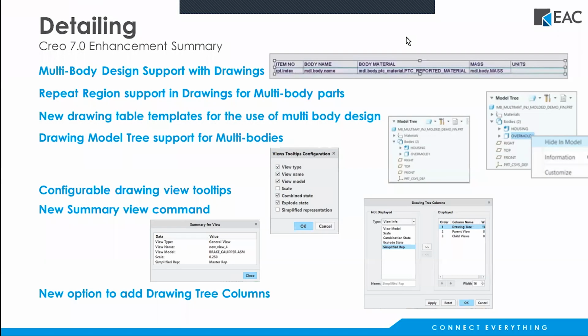One was, can you undo the two bodies to make them one? You can add them together. You can just go and redefine body X and change it back to body 1 or whatever body you want. That's how you would do it.